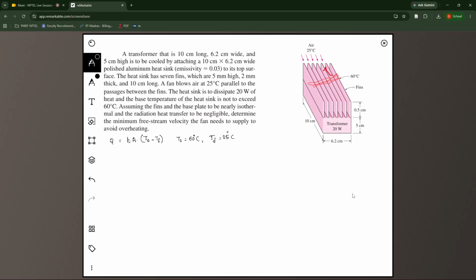Even within channel flows, if the internal distance between the plates is given by b, and 2 times the boundary layer thickness is less than b, then you can actually use the flat plate assumption.